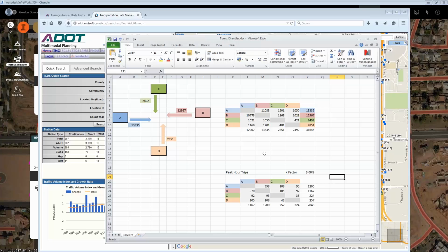The other thing that we need to do is try and figure out what the turning counts are. So we know how much traffic's going along this road here from west to east, how much of it is turning and going south, how much of it's turning north, and how much of it's just carrying straight on. Now, a simple way of estimating that, and it is only an estimate, is to look at the relative flows on each of the streets and do some calculation in here to divide up that flow proportionally. That's already done for you in the cells here. That's an example, as I say. If you have no other information, that's as good a place as any to start with what the traffic's like.